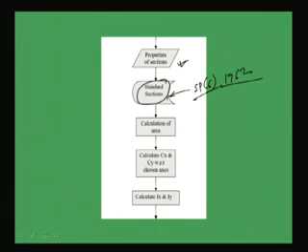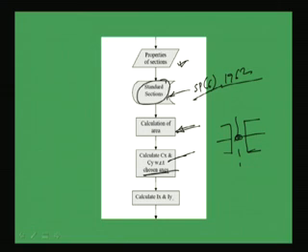Then we will find the area of the equivalent section, area of the built up section, where we will find other properties also, like center of gravity with respect to a chosen axis. Some axis is there, suppose this is one section, this is another section. So center of gravity, we can find Cx and Cy with respect to that chosen axis. Then again we can calculate Ix and Iy, the equivalent moment of inertia about x direction and y direction, that also we can find.